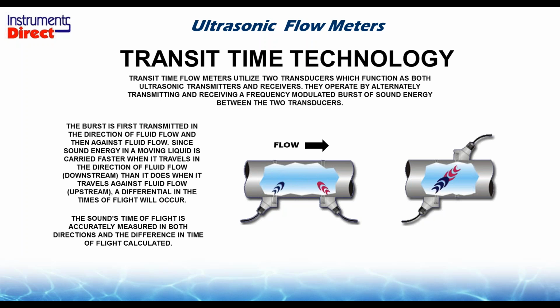So lift station applications are usually okay for a Doppler. And a lot of times the straight run of pipe is not long enough for a transit time flow meter on a lift station application.